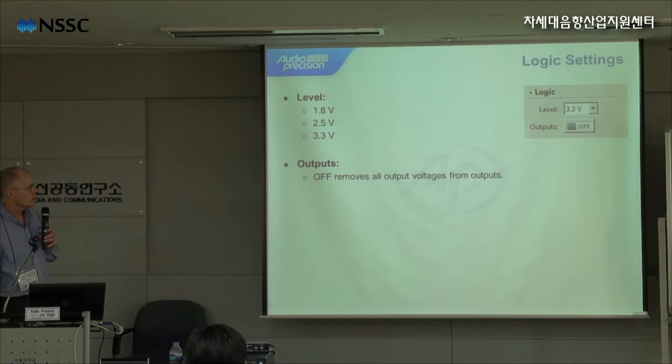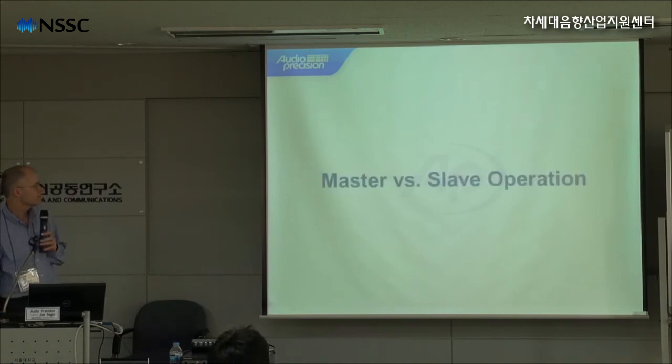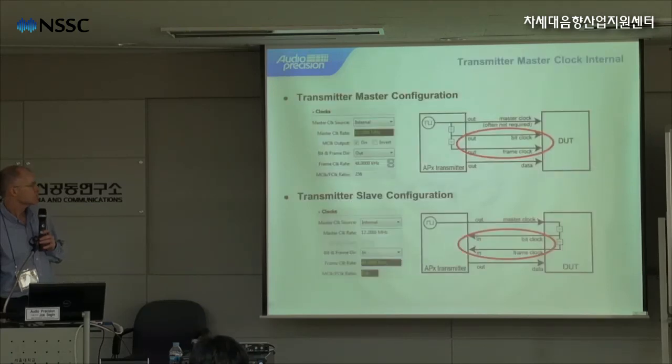And then there's a logic on-off button, which, when off, removes all of the output voltage from the outputs. Now, master versus slave operation. In the transmitter master configuration, the bit clock and the frame clock are going from the APX transmitter to the device under test.